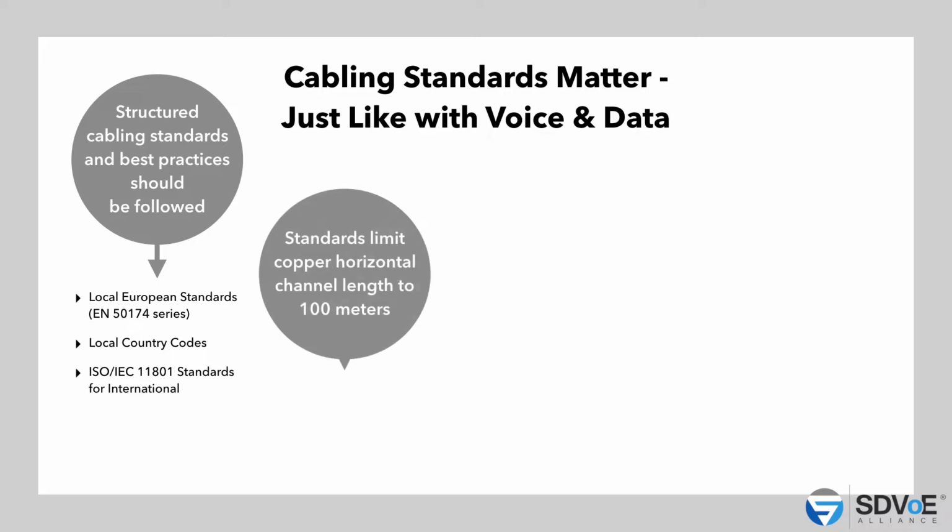So typically for a standard, if we're running say 10GBASE-T, we're running that up to 90 meters on what we call a horizontal link. We call it a permanent link, and then if we want to extend it, we give ourselves an extra 10 meters for patch cords at the end. And that's a really important thing about patch cords, because without having really ultra specialist equipment in terms of AV cables, we're going to be using a Category 6A or a Category 7 cable, and we'll be plugging it straight into the end device.